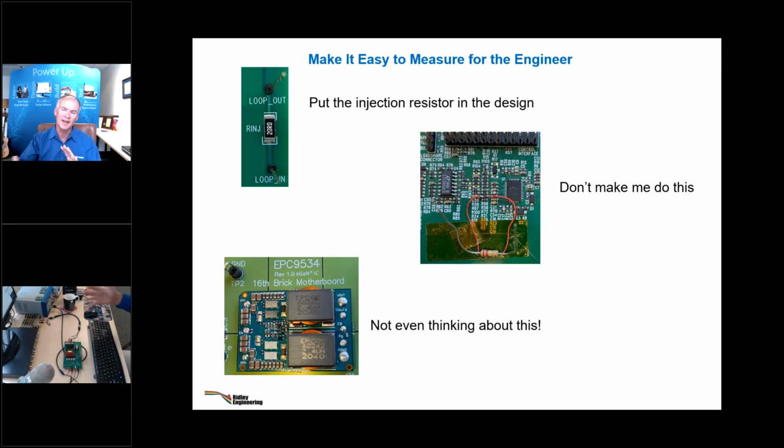You're definitely moving the set point of the controller when you're putting 100 ohms in there. So again, nothing magic. Middlebrook, of course, didn't use a resistor at all. He just had a loop of wire and made it part of a transformer. The only problem with that is the signal size is not going to work very well.